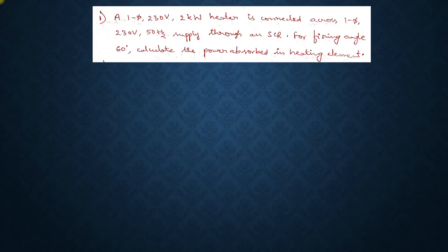Okay, the first problem is: a single phase 230 volt 2 kilowatt heater is connected across a single phase 230 volt 50 hertz supply through an SCR. For firing angle 60 degree, calculate the power absorbed in the heating element.